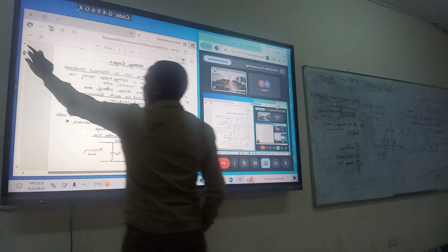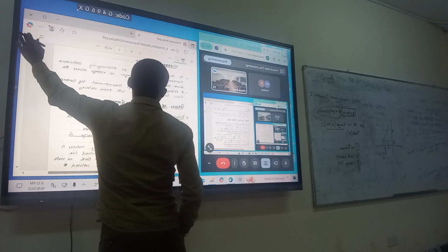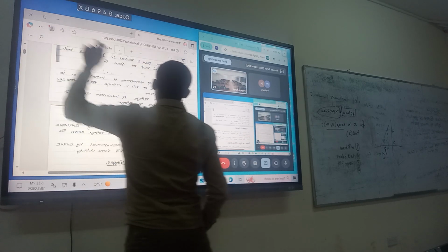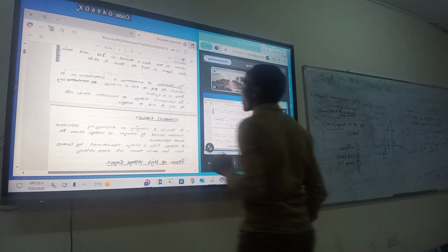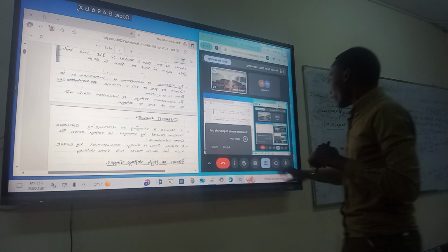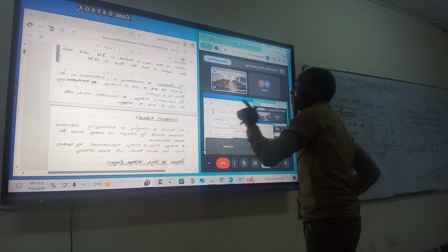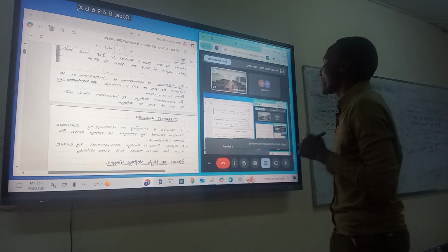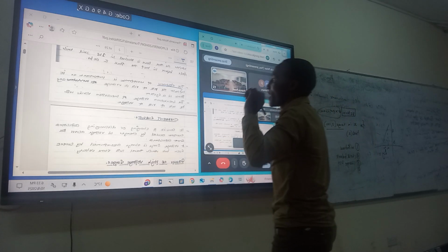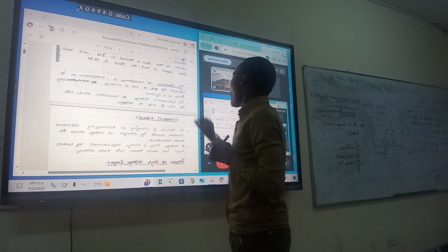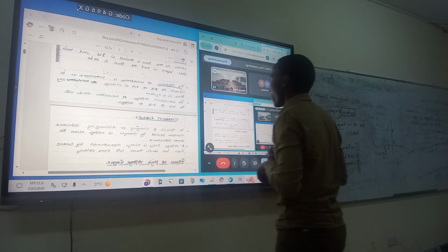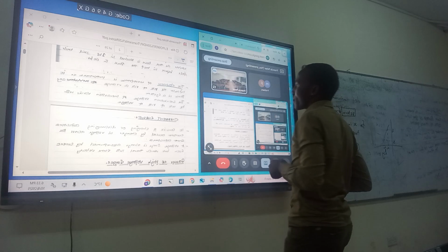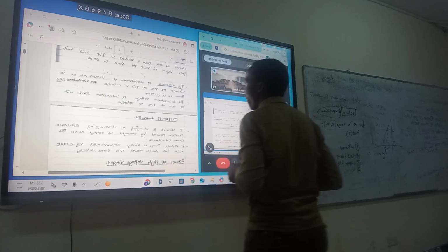There is something I want to say here. From the graph, the steepness of the wavefront is important, as it indicates the rate of rise in voltage at any point in a system. That means the breakdown voltage of the insulation varies with the rate of rise of the voltage.